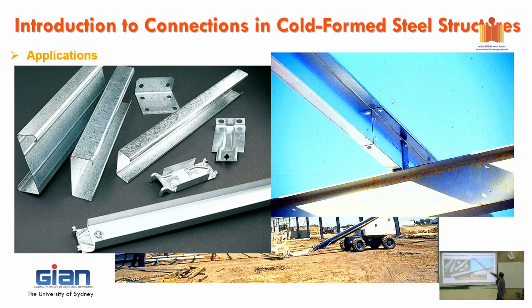And this is how we built our purlin system in Australia. We normally use a Z section, and we overlap that over the support, so we get the hogging moment. That's what we do to make sure that the beam here is a continuous beam.